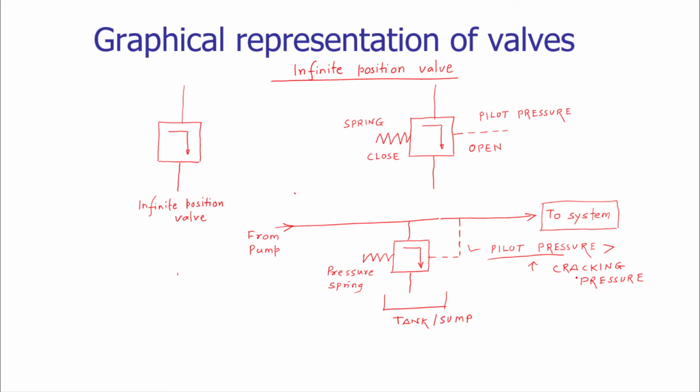So how to decide the cracking pressure? How to provide the cracking pressure? For that purpose, we have to use the screw. The screw based arrangement is utilized, and that has been shown by using an arrow which is put over the spring. The meaning of that arrow over the spring is that we are setting the pressure. So we can set the pressure here by using the screw arrangement.